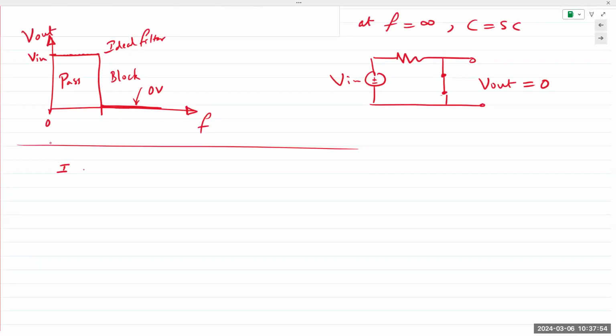I can be determined as voltage V in divided by the total equivalent impedance in the circuit, which would simply be R plus ZC. Again, this derivation is not important, especially since we don't do this for the non-EE major classes. V in over ZEQ. ZEQ in this case comprises just the resistor and the capacitor impedance. That's it, R plus ZC. So this gives you V in over R plus 1 over j 2 pi FC.